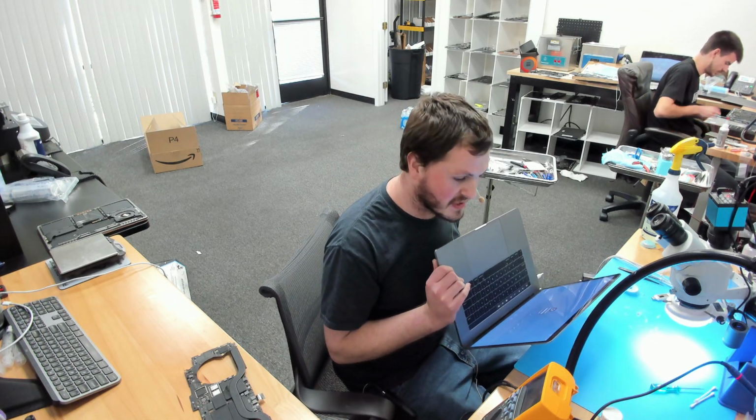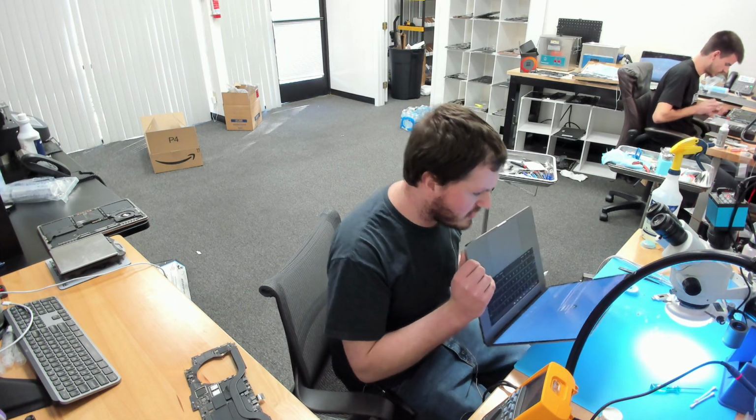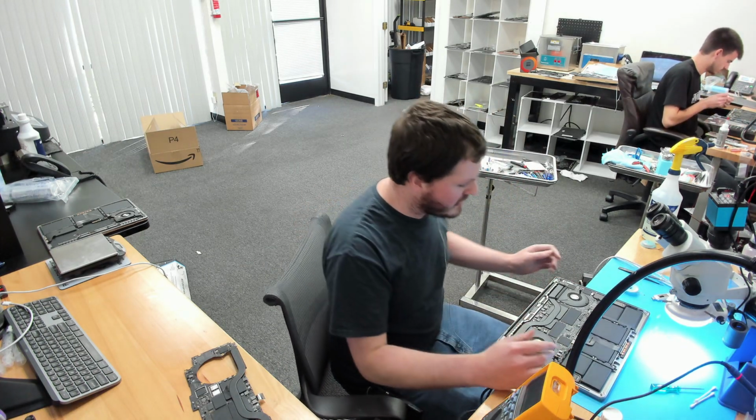All right, so we're done with the DFU revive. Luckily, the data is still retained, the device boots, and we can give some happy news to this customer. But all looks good here. Now we're just going to go ahead and put a little conformal coat on our 2V5 NAND regulator and reapply our thermal compound, and that's pretty much it. This is good to go for the next foreseeable future, really.